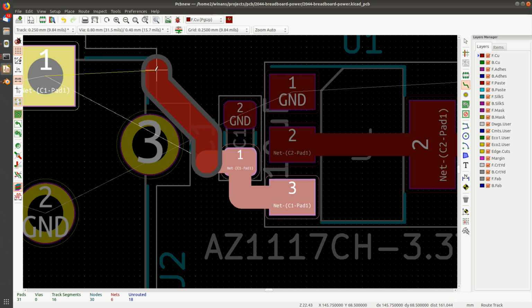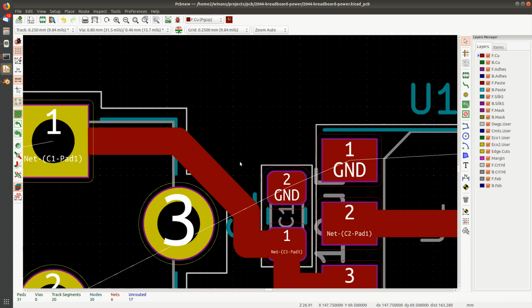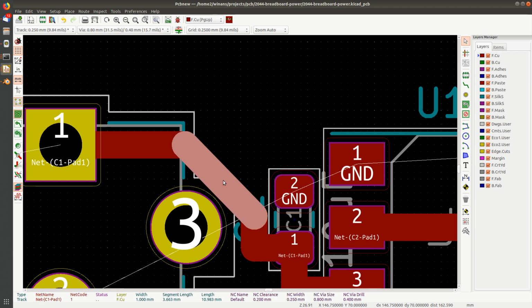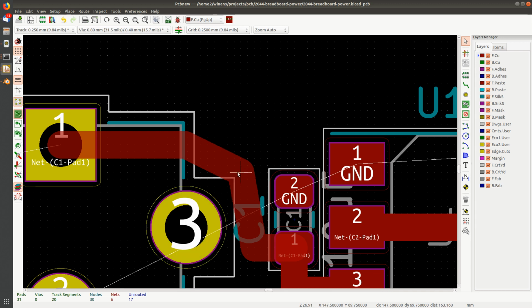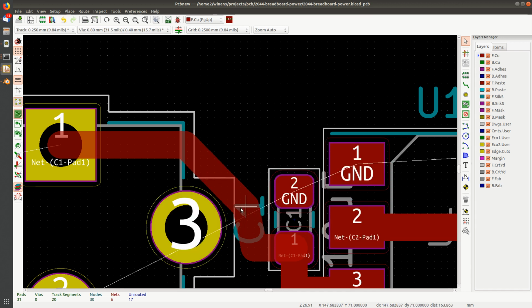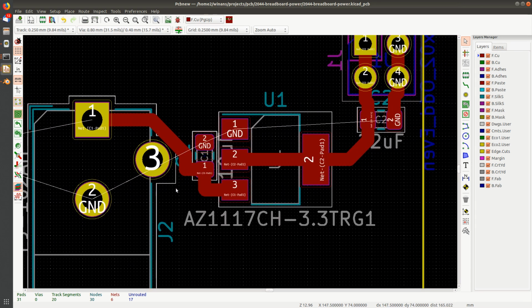I could do that. Sure. And I'll show you another thing now. I'll hit escape. So remember, the pointer moved from the track to there when I hit escape. If I click this and I hit, I think it's G, I can mess around with it after I've routed it, and clearly I could even put it where it doesn't want to go. If you really want to do something fancy, right? Like maybe I want to do this or whatever. Yeah, sure, whatever. Leave it there. So you have quite a lot of options on how to draw copper lines and things on here.